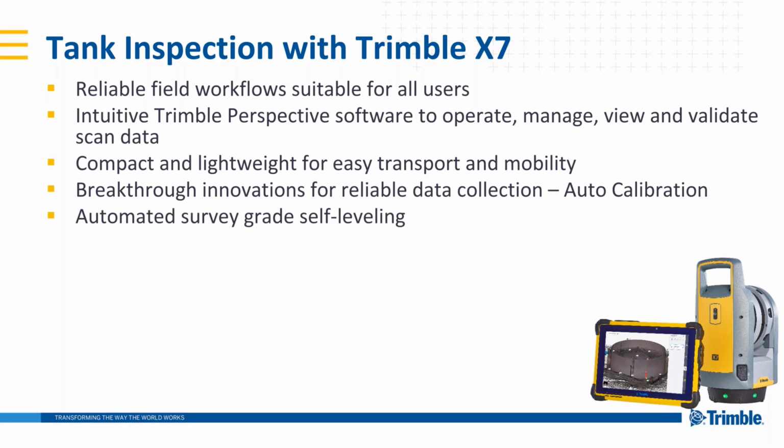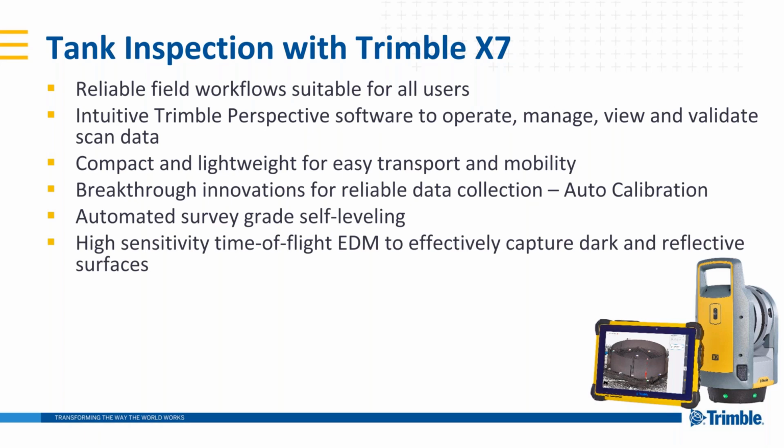So another intimidating thing about scanners was trying to spend the time to learn how to get them level on a tripod. If you didn't have a lot of survey experience, this could be time consuming. With this scanner, you just need to get it close, and then the scanner will take over and finish on its own to apply this leveling compensation.